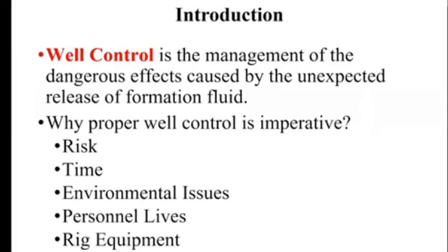Basically, well control is not an issue when we are drilling through an impermeable formation. When we are drilling through permeable formation and formation fluid starts entering the wellbore unwantedly and unexpectedly, we should be able to manage the situation in a safe manner. This is basically called well control.